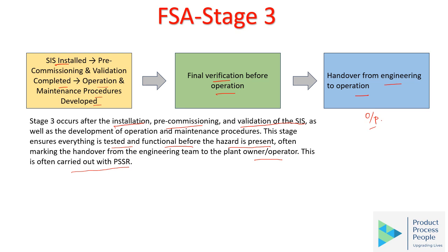At stage 3, when the plant is about to commission, procuring additional transmitters, installing them, and commissioning them is almost impossible. That's why it is advisable not to do stage 3 directly, but to do stage 1 and stage 2 also, and then come to stage 3.